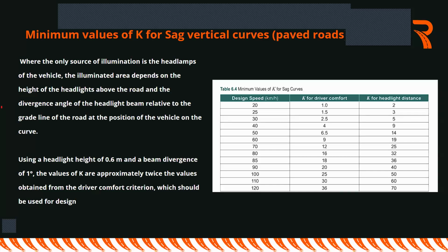That is where you find bridges. That's where you find culverts. That's where you find many outlets to various catchments. While, of course, the crest curve also has a consideration on the drainage. Mostly, you will notice that when you provide a drainage structure at a crest curve, it is sometimes more of a river that is splitting some water so that it can go downhill and also across the road or section. That's just an observation according to the topography of most of the areas.